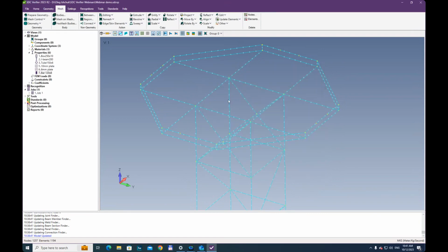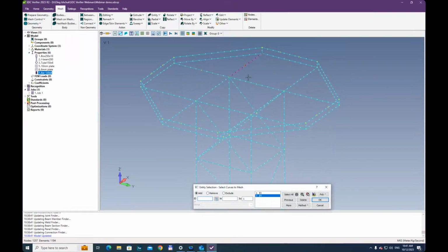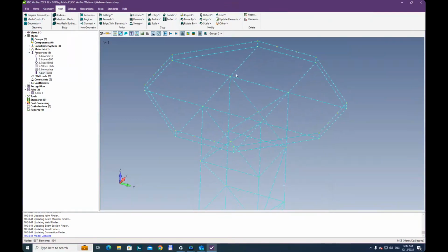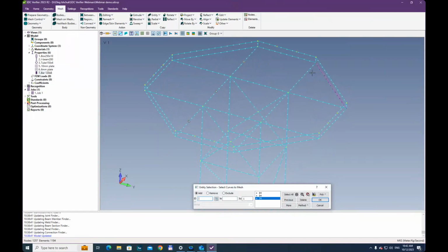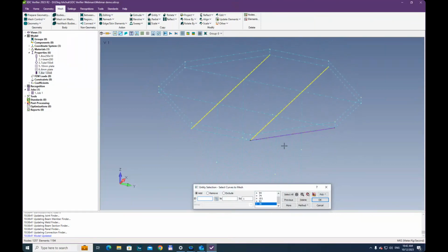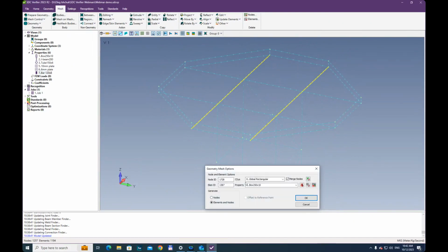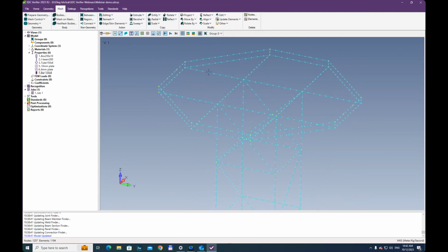The property has been created, and now let's mesh this final line. So geometry surfs, we select all, we also would need to define the direction. So first we mesh these ones. I mesh 1, 2, 3, 4, 5, 6 lines, highlighting those lines for you now. The y direction for them will be global y. I'm defining this property of bar 12x8, and the y direction is going to be global y. Pressing OK. Switch the elements on.